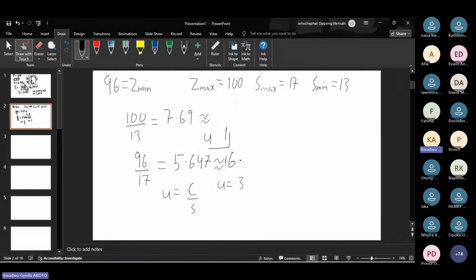So we know that this is a lap winding, so our number of parallel paths A is equal to the number of poles we have, right? And we've been given our number of conductors per parallel path, right? So if number of parallel paths is equal to number of poles, then I can also assume and call it our number of conductors per pole, right?